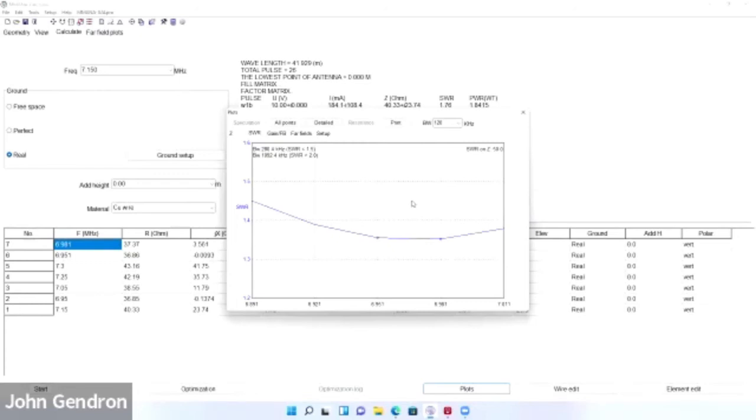And when we talk about resistive loads, that is where you get maximum power out, okay? When you're purely resistive, whether it matches well or not to the antenna, all the energy being sent is radiated. None of it's stored, it's all sent out. So don't equate a good SWR to resonance. A good SWR is important, don't get me wrong, but it doesn't mean your antenna is good.